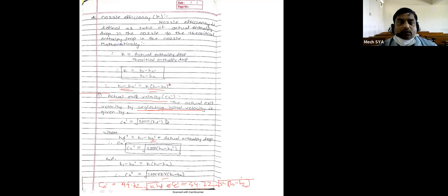Submit over. Sir, what is K in the formula for C2? K is the nozzle efficiency. Prerna, we already defined nozzle efficiency. H1 minus H2 dash is equal to K into... by definition, K is equal to actual enthalpy drop divided by theoretical enthalpy drop, and K is equal to H1 minus H2 dash divided by H1 minus H2. Therefore, actual enthalpy drop H1 minus H2 dash is equal to K into H1 minus H2. Understood, Prerna?